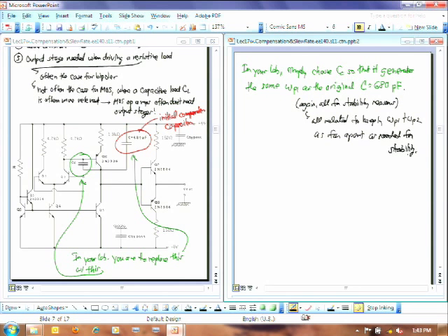Yeah, you're right, actually. It depends on what the gain is across this Q6 here, because that gain can be a pretty significant factor. So it's not going to be as small as it could be, this C sub C. You're right. If this had an active load here, if this had a current mirror load with a much larger resistance, this would be extremely small compared to that 680. So as a consequence, I think it's going to be smaller, but it's not going to be 1 picofarad or so, right? It still may be a significant number there. Okay?